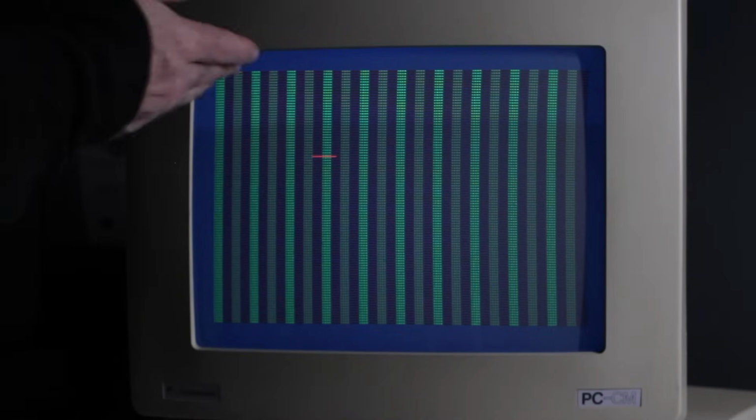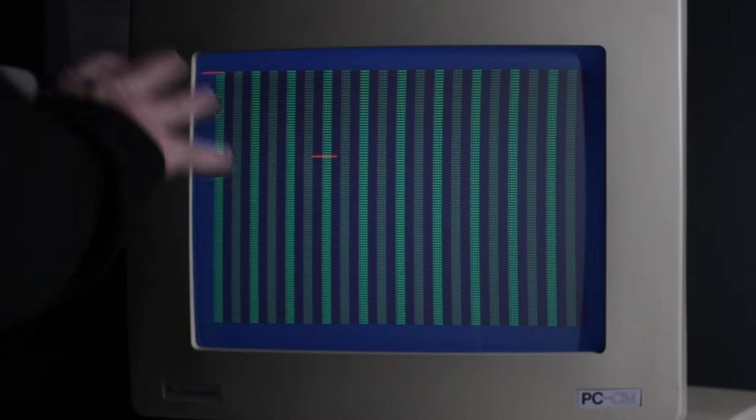So I actually don't know exactly what's going on here, but what I think is happening is that for each pixel within a character, it has a formula for how long it should make the CPU wait. And the only problem is that we have no idea whatsoever which pixel of the character our write request is going to arrive at the graphics chip. And the reason we don't know is because the CPU is not in sync with the graphics chip.